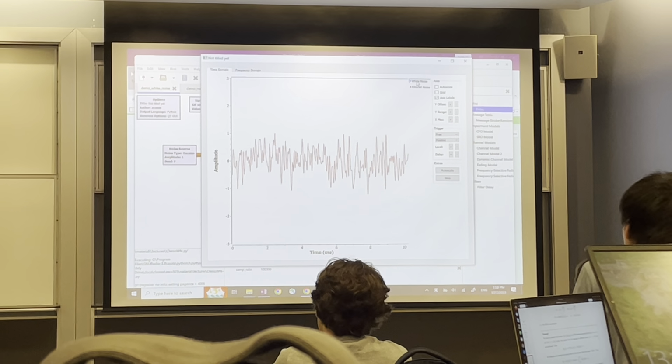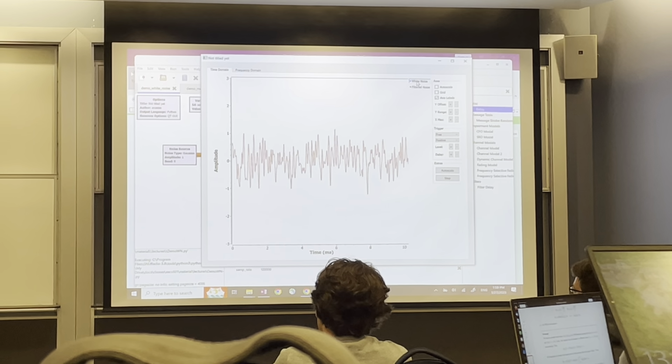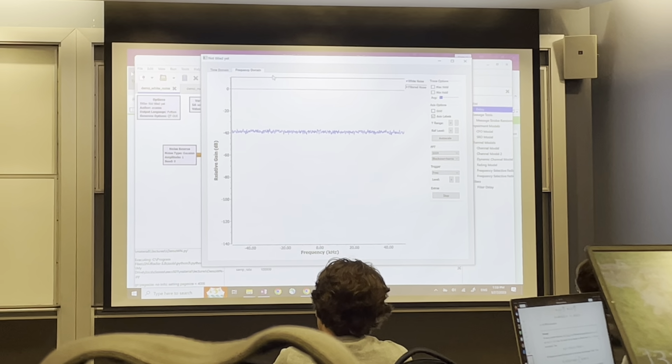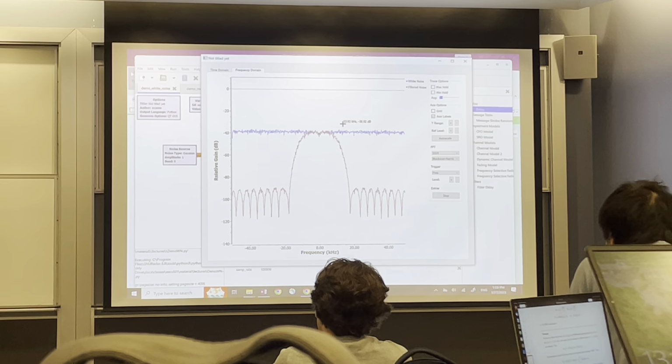What is its power spectral density? That one. This is nothing else but Sy of omega equals Sx of omega times the magnitude of H of omega squared. Sx is 1, it's constant, and so what you see here, this red curve, is nothing else but the frequency response function of my filter, which is a low pass filter.